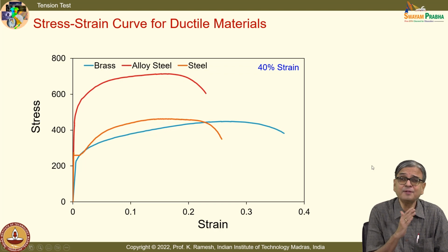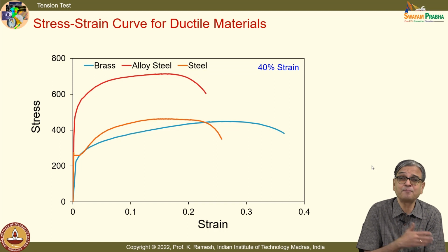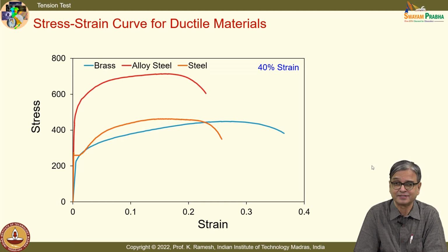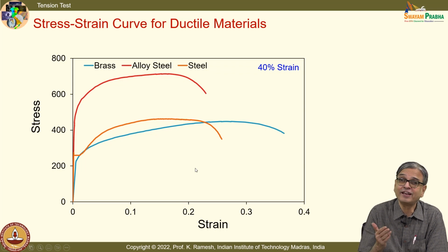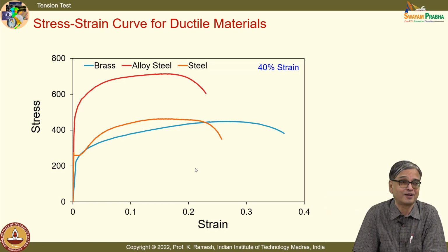But there is another important observation, let me see whether anybody makes it, which is important from your strength of materials point of view. Because why do you do alloying? You want to improve the material characteristics. By alloying, you have been able to improve what? You have been able to improve the yield strength. Can you do anything with the Young's modulus? What does the graph say? Does the graph give you some clue on what happens to Young's modulus by alloying? How do you say it increases?